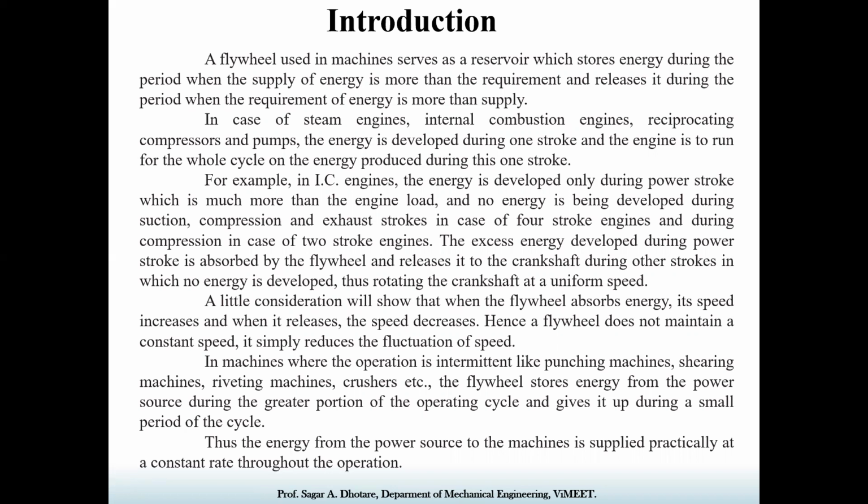So that energy we can utilize for further operations. Okay, so we can store that energy which is created particularly at a power stroke, and which can be used further to develop suction stroke, compression stroke, and exhaust stroke.